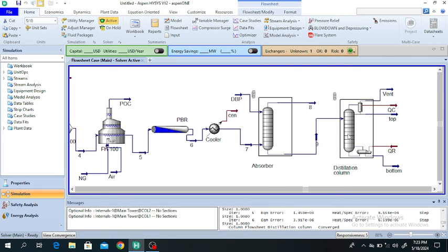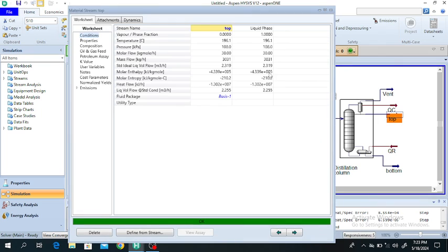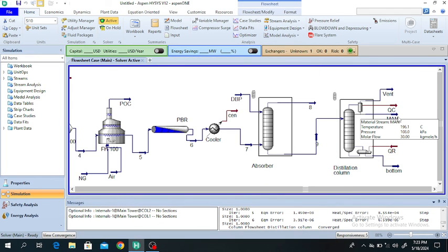In order to increase the purity of the maleic anhydride, this is the top product, and I will rename it maleic anhydride. In order to increase the composition of maleic anhydride to 99%, 99.2%, or 99.3%, you can recycle this bottom stream